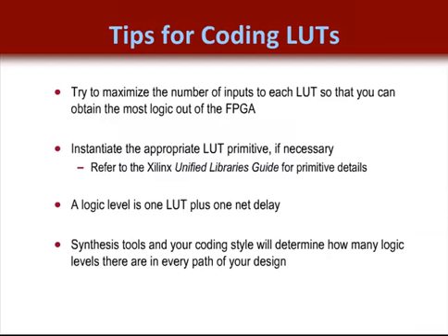A logic level is 1 LUT plus 1 net delay. So whenever we talk about multiple logic levels, we're talking about multiple nets and multiple LUTs cascaded in series. Synthesis tools and your coding style will often determine how many logic levels there are in every path of your design. But this, of course, will vary. But we're going to look and try to highlight in this presentation a number of cases where the coding style is pertinent.